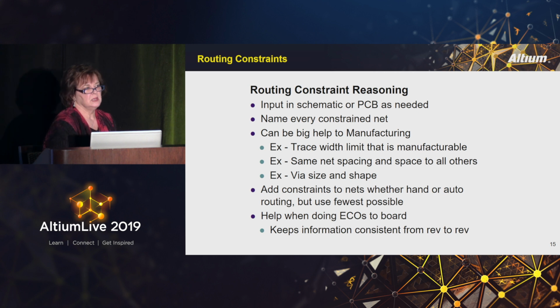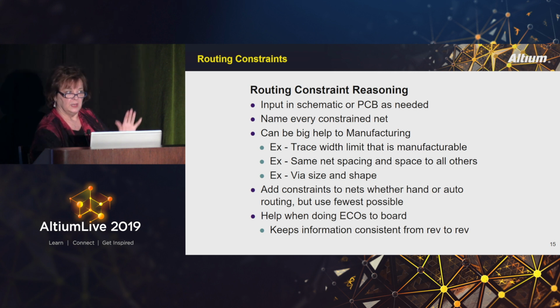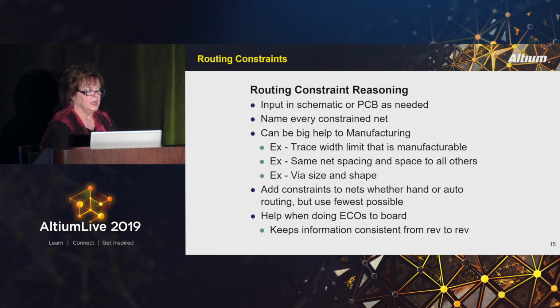Routing constraints, just a very brief slide on routing constraints. Be aware of them. Certainly Ben's going to talk about them a little bit. They can be input from the schematic, or they can be input from the PCB. In my company, I'm the one who gets to do that, and that's fine with me. The one issue about that is I, as the designer and not the circuit designer, need to be sure that when the engineer places parts on a schematic that are next to each other on the schematic, I need to know that what he's thinking is those parts go next to each other on the board itself.